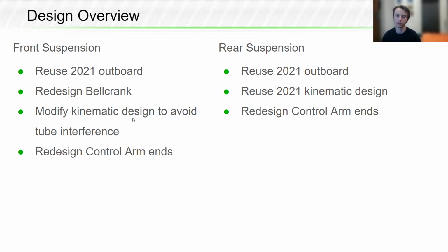So we're repositioning the control arms to avoid tube interference. And that also means we redesign the control arm ends. So we're tweaking the 2021 suspension. And for the rear suspension, we're reusing the outboard and we're reusing the kinematic design as well, designed by Victor, who's in the call. And we're redesigning the control arm ends for manufacturability.